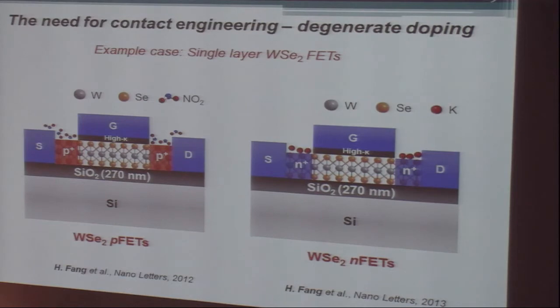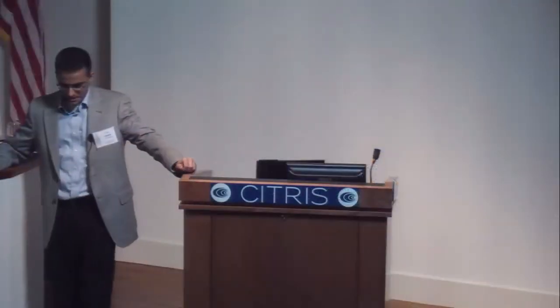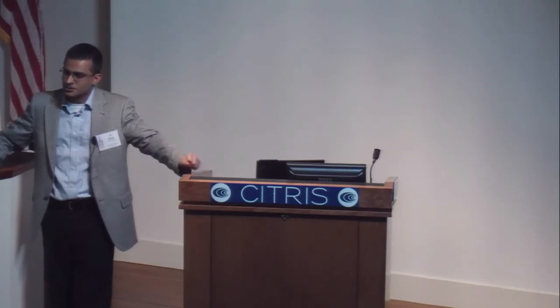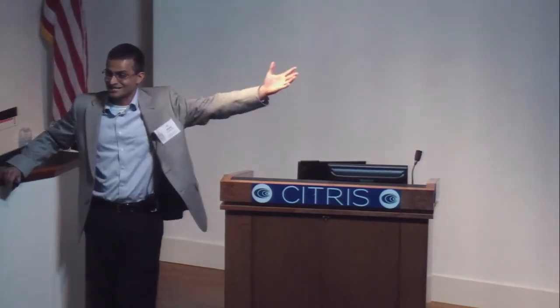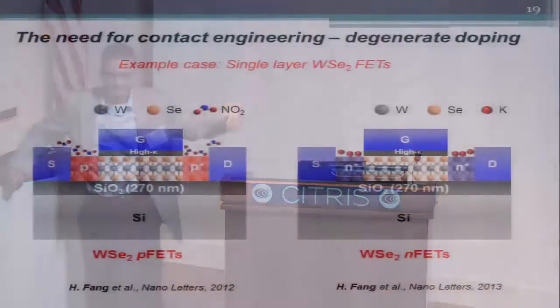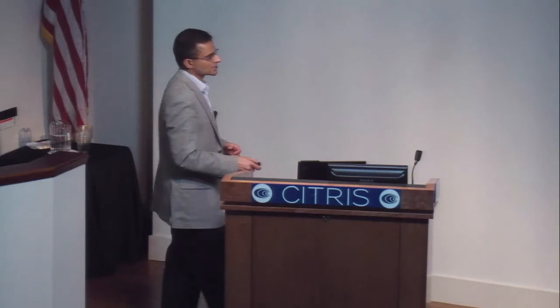When the material is very thin, it's now well established, whether it's organics, a carbon nanotube, or indium arsenide quantum confined, which we have shown in our group, that you can use a concept known as surface charge transfer doping. We employed a technique that was known previously mostly for organic materials and carbon nanotubes on these chalcogenides.